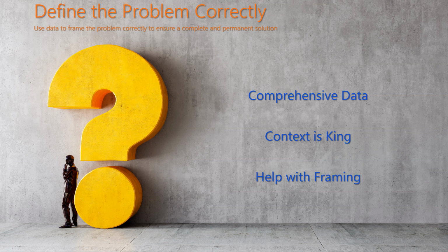An example of this would be when the data being collected shows that a machine is failing during first shift much more frequently than other shifts. Then the team jumps to the conclusion that the first shift operator must be doing something differently than the other shifts and focuses the root cause analysis on why that's the case. But in actuality, the project team has an engineer watching the machine during first shift, and they're counting on the other shifts to self-report when the downtime occurs. And so this manual data collection ends up biased because the downtime is driven by something else, but the data collection process itself is leading the team to the wrong conclusion.